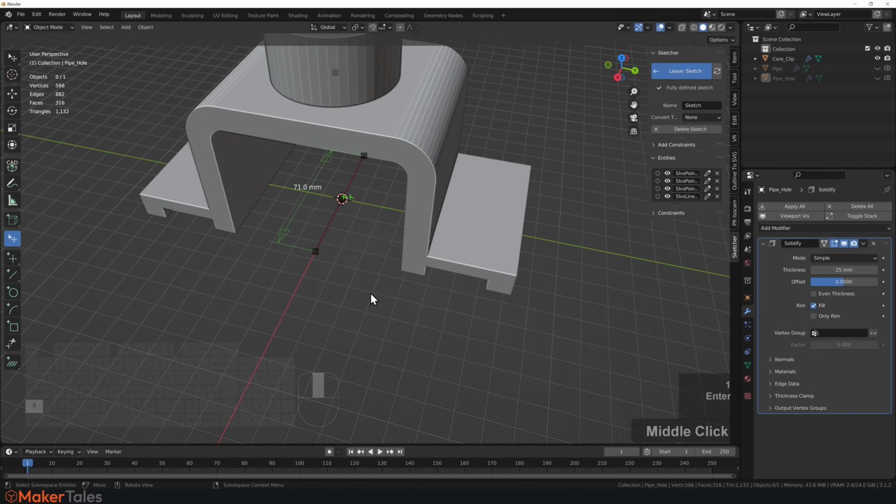And now let's bring in the hole. Now I'm going to mirror this all the way around, so I only need to bring in one. So I'll press C, make a circle here. Let's do the diameter of this one, so let's go Alt O. The diameter that is set for this is going to be 12. And then here's the tricky thing. I need to reference off that line and then the origin, I'm pretty sure.